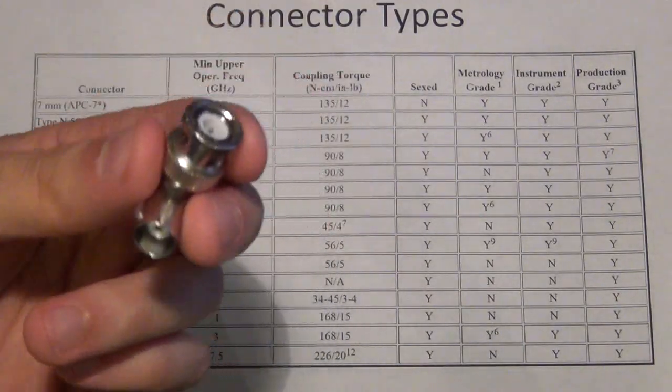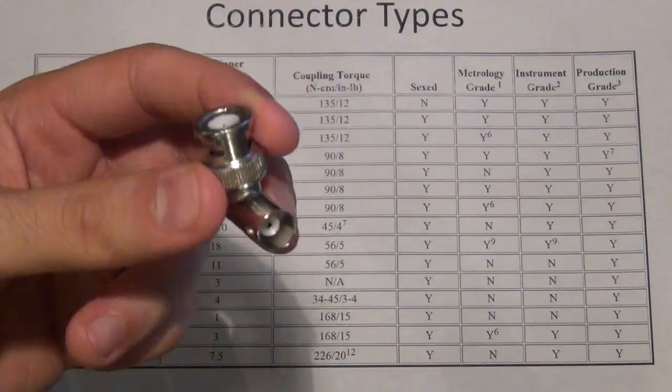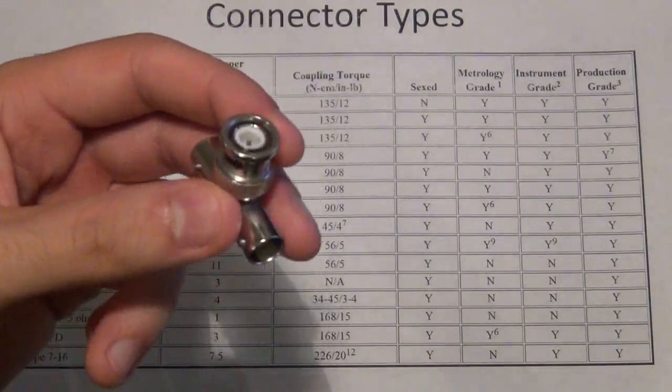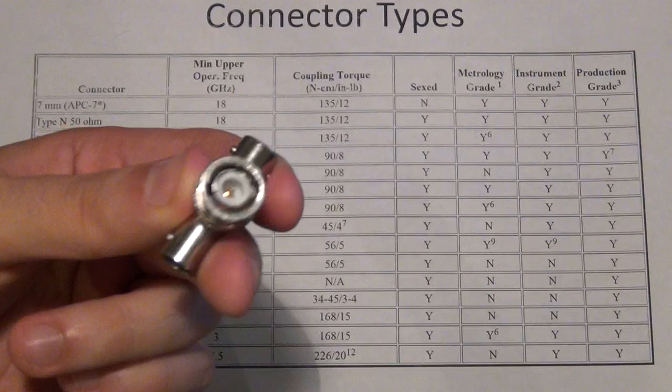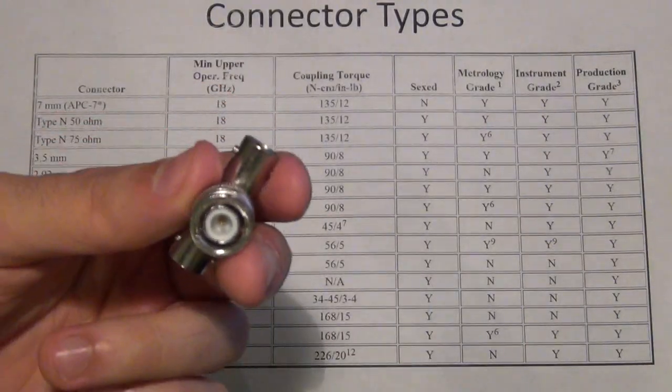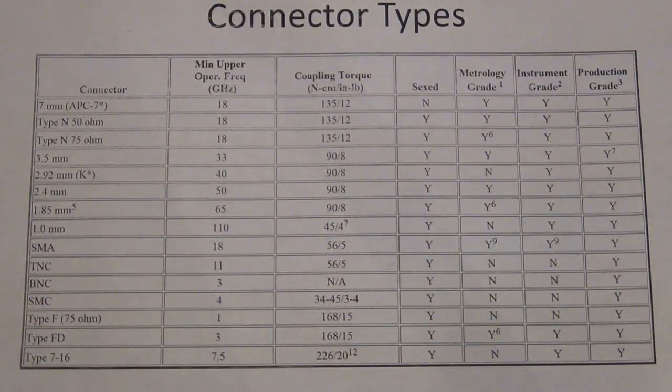And anyhow, this one is intended for very low frequency. Anyway, this is not a 3 gigahertz BNC connector. So you have to also be careful with that. Just because it's BNC, it doesn't mean it's going to work all the way to the rated 3 gigahertz.